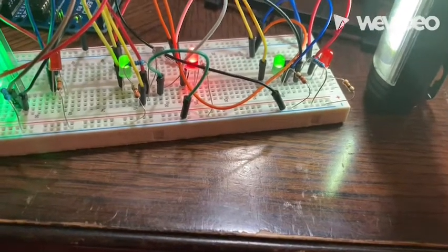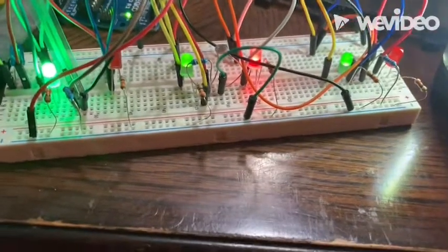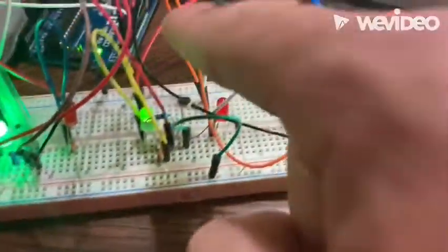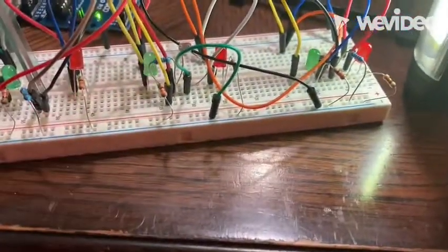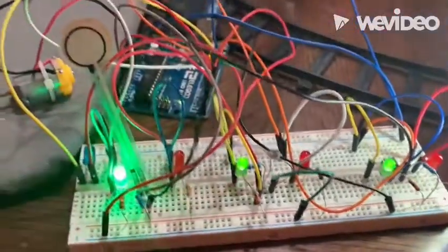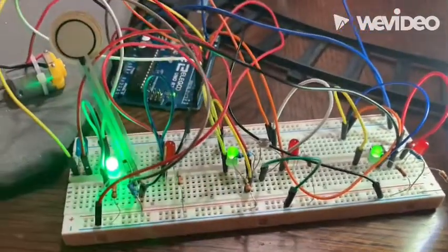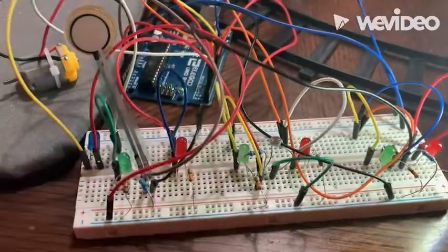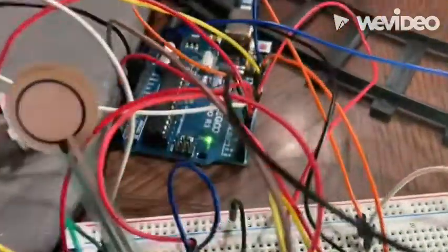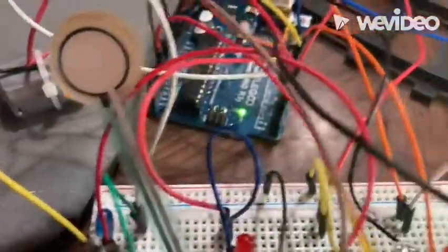So with the photoresistor, I have to take light away for it to activate. And you can see that it's gone to processing now. So again, I have to go back, press the input again, that's greater than 0. And the motor will start again, moving the conveyor belt.